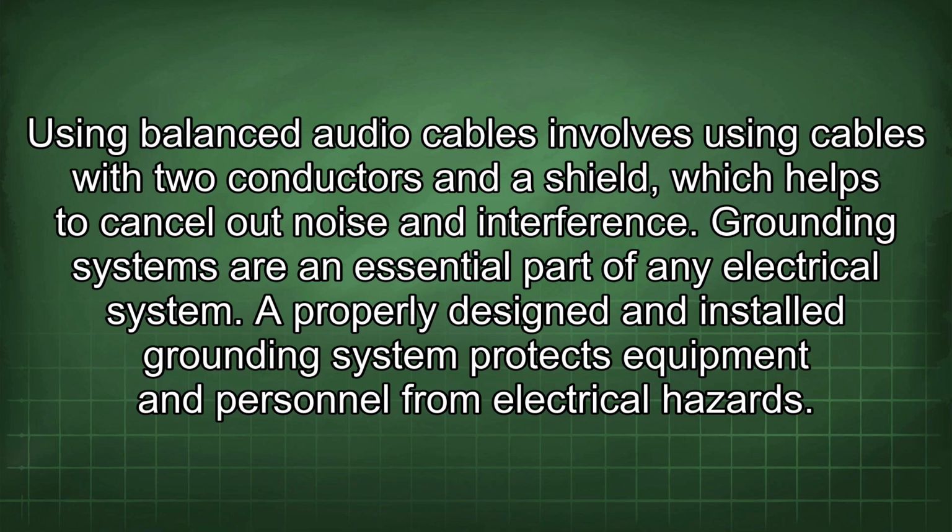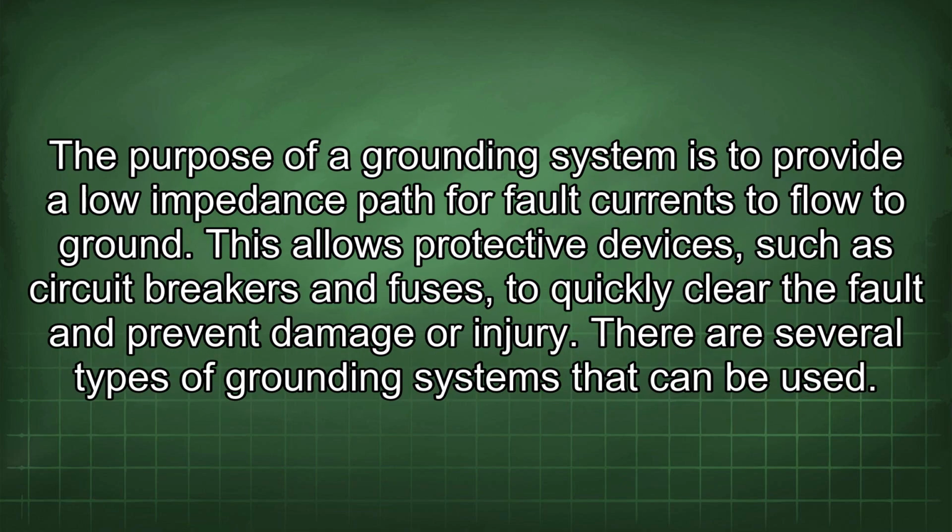Grounding systems are an essential part of any electrical system. A properly designed and installed grounding system protects equipment and personnel from electrical hazards. The purpose of a grounding system is to provide a low impedance path for fault currents to flow to ground. This allows protective devices such as circuit breakers and fuses to quickly clear the fault and prevent damage or injury.